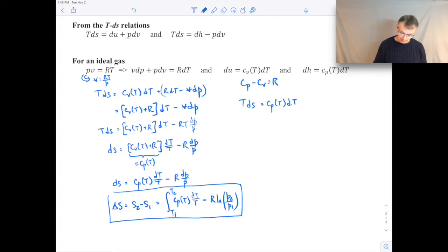You know what, this expression is incorrect. I just realized that. That should not be minus PdV, that should be V dP. Sorry about that, I need to make that correction. So what I'm going to do is make use of this expression here for that one. I just have my TdS equation incorrect. So I'll make use of this with that. And then that becomes, let's see, a plus, oh, I'm sorry, this will be a minus R dT plus PdV. Okay, so what I've done is I've just taken this expression, substituted it in here, and that's what I get here. Now let me go ahead and combine some terms again.